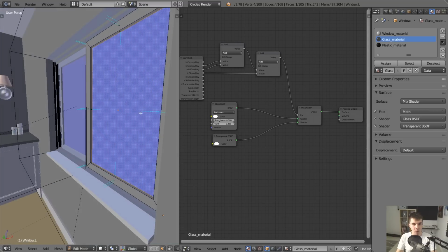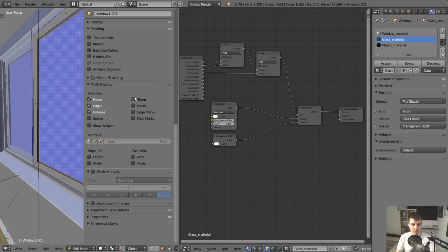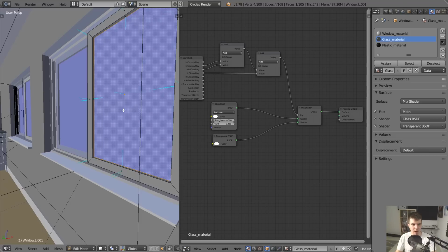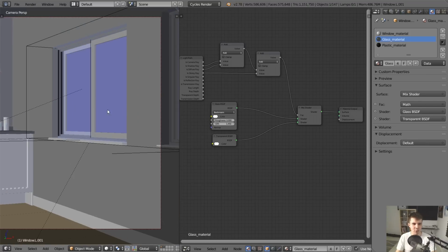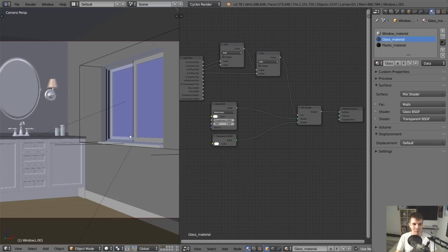So you can fix that very quickly just by selecting that plane and hitting Control-Shift-N. And now it's pointing inwards. Okay, so again, I think this is a bug. In fact, I'll probably suggest it to the creator. I think he messaged me on Twitter. I might reach out to him there and just let him know that those should be pointing inwards. Maybe I'll let him know about the little windowsill problem as well.